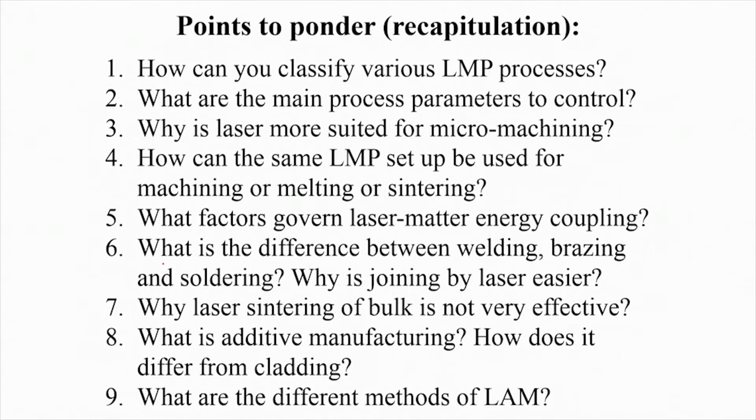We saw that using laser we can do all kinds of joining processes, welding, brazing, soldering, and using laser these joining processes are so easy because I can do it in air, and I can do it for dissimilar things, and I can do such joining processes even for non-conducting materials, non-electrical conducting, and so on. So I can try and join even an insulator with a metal.